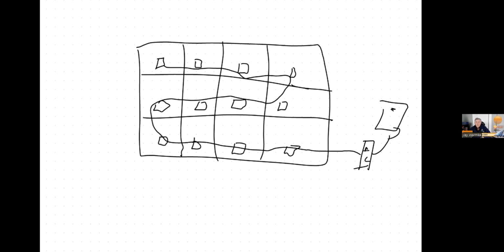Well, if this same shading took place, let's say it took place here, it would affect a little bit of the output of this panel, but none of the other panels are going to be affected, because the MPPT is on each single panel. So each single panel is going to produce to its maximum. That's one reason why you use microinverters or any module level power electronics, MLPE: it has an MPPT on every single panel. And as you get into it, you're going to find that can be a really big deal.